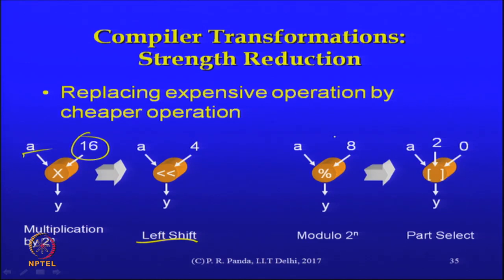These are the class of optimizations that somehow lead towards simplicity. That simplicity it makes sense to argue about, even if for example, you do not know anything about the target architecture, whether it is an ASIC, whether it is an FPGA, whether it is a processor. The target architectures can be ignored for most of these optimizations. Some of them are interesting because they may represent trade offs, but often the simplification operations make sense to move in that direction. Remember that they may or may not result in improvement all the time, that does have a dependence on how you realize it, but it will not be worse, it would usually be better than or equal to.